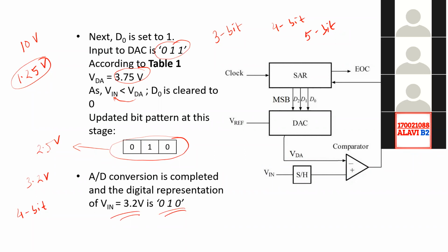We need converters with higher bit capacity. Well, obviously we need converters for higher bit capacity. The DAC that we would require would be necessary to be able to convert higher number of bits into the equivalent analog form. But one more thing is that the SAR checks or decides for 1 bit at a time.